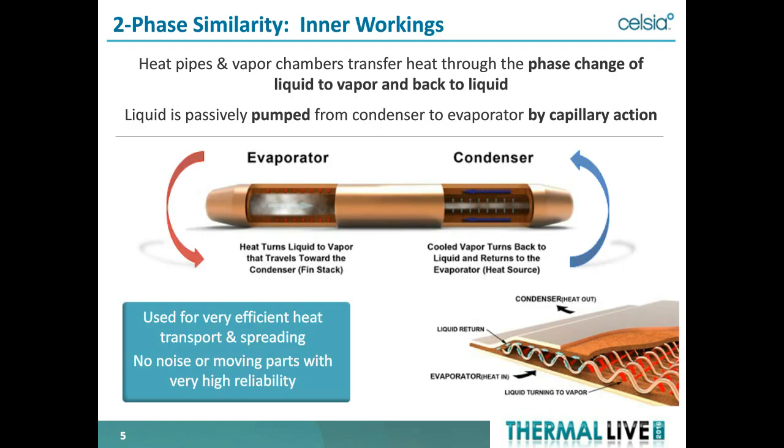So I think everybody has seen these slides. Probably everybody understands how these things work. The key takeaway that you want to keep in mind here, because it's a question I generally get, is that these devices are vacuum devices. So they do work below the working fluid boiling point. And the limit to the performance of these things is usually the capillary limit, and that is getting the fluid to be returned back to where the heat is taking place.